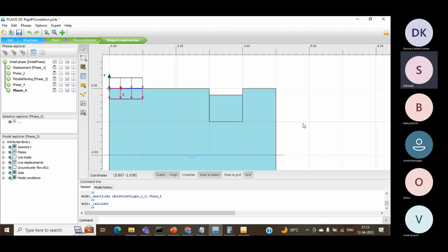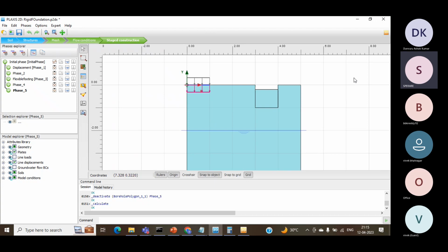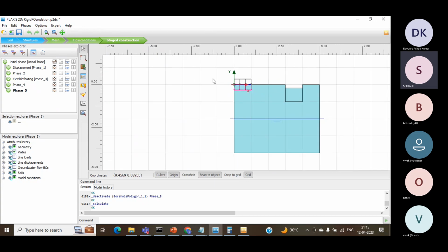So these are the suggestions that you can give to the site engineers when you are excavating at the site. You can go for this particular depth without any consolidation. I mean, you don't need to wait for particular times. You can excavate, and after that, you can leave it for consolidation, and again it will stabilize. And then you go for another day of excavation. These are the kinds of suggestions that you can make to the site engineers. So this is how you can solve these excavation problems. And there are many other things, where you can add supports and so on. Slowly we are going to discuss those things.